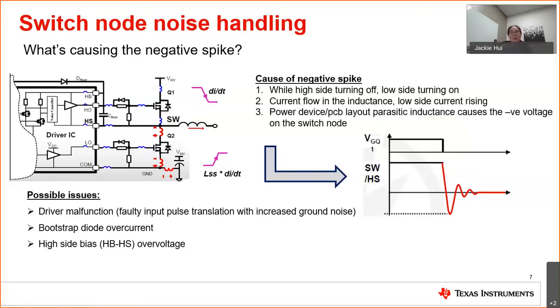This can cause potential issues to the system. For example, it might cause driver malfunctions, because this noise can couple to the ground and affect the driver translation of the input signal. It may also cause bootstrap diode overcurrent.